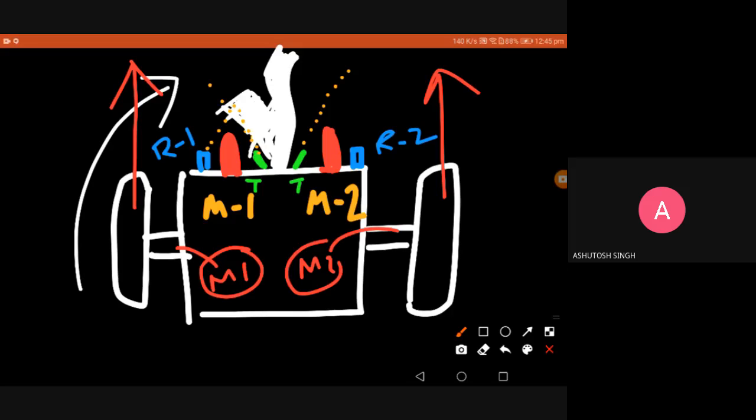When both sensor receivers are not getting high, not receiving any radiation, that means the white line is equidistant, its center is towards the center of my robot, passing in between the two wheels of the motor. So I don't need to bother about anything. I can go straight.